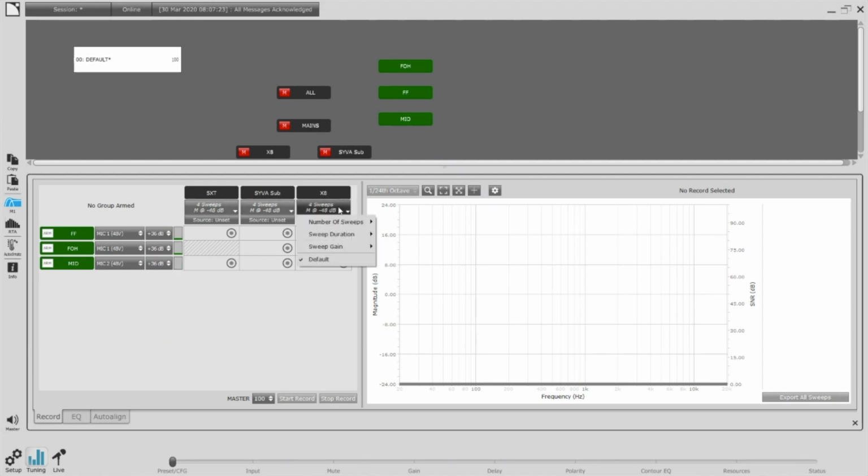For each of these, you have a choice of some settings of your system record. So things we can do, for instance, are set the number of sweeps, and then we're going to listen to this in a second, but what M1 uses is an impulse sweep versus pink noise. We can have it do 1 to 10 different sweeps. And real simply, if you're indoor and you're close range, 1 works just fine. If you want to check to make sure there's not too much variability, you can set that to a higher number.